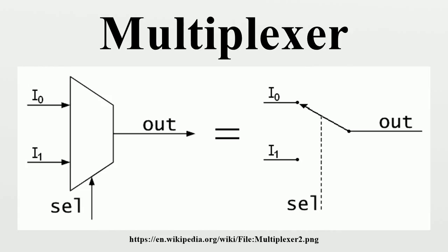Often, a multiplexer and demultiplexer are combined together into a single piece of equipment, which is usually referred to simply as a multiplexer. Both pieces of equipment are needed at both ends of a transmission link because most communications systems transmit in both directions. In analog circuit design, a multiplexer is a special type of analog switch that connects one signal selected from several inputs to a single output.